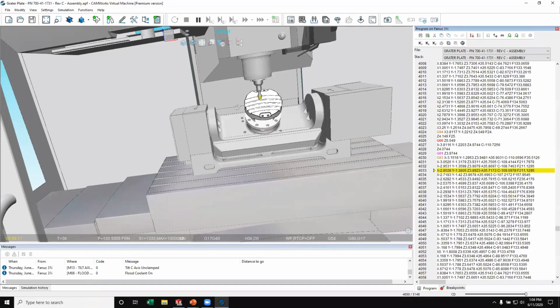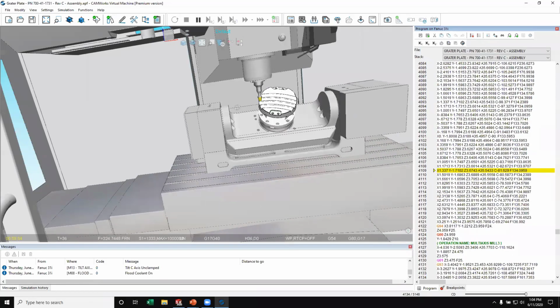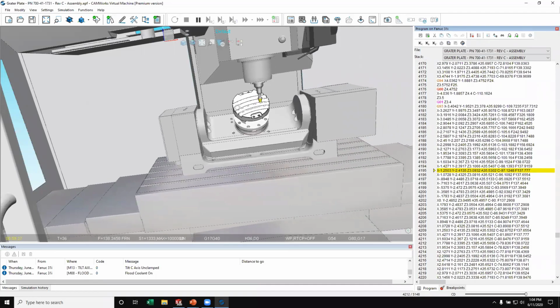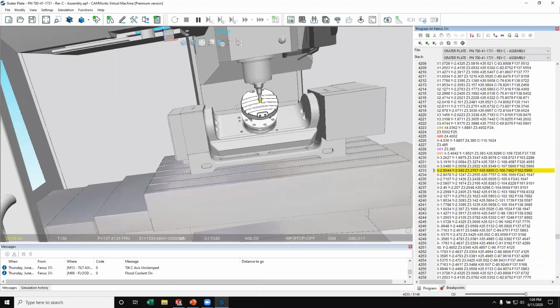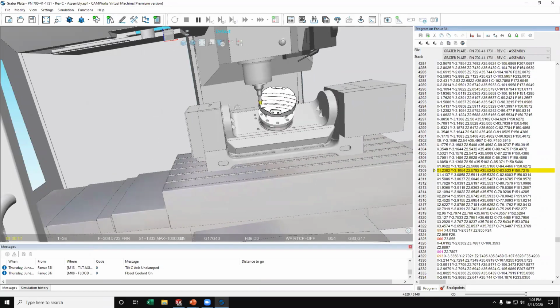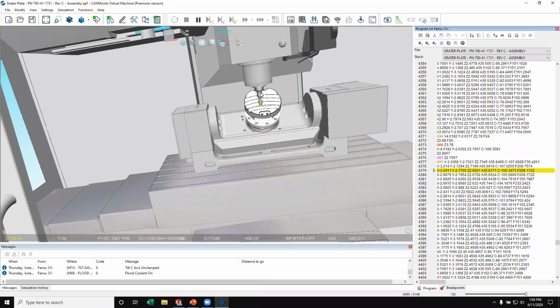You can see the rotary and the tilt axis both moving there. And then when we do the swerve cutting, you'll really see the rotary and tilt axis move there. And that's when the things are real nice. You got to watch tool clearance and stuff on the back side and the top of this part here.